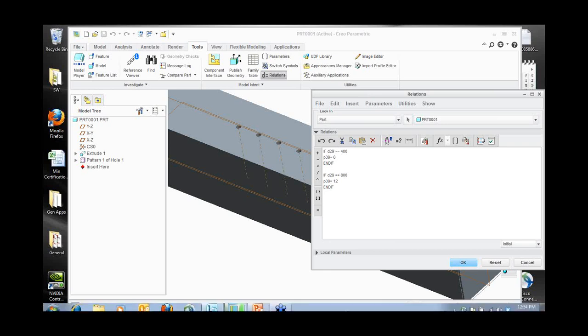I was working with a customer, and we also did this for parameters, right? If the parameter value is equal to this, or how about this? If the parameter value doesn't have a value, put in a dash. If it has a value, then you're good. But we actually put it in so that at that point in time, the repeat region would fill out correctly. So if they had a user that didn't fill it out, it would actually put in a dash, so they would get a dash and they can see that instead of the repeat region kind of freaking out and not filling out the way they want it to. All right? So this is conditional statements within relations.